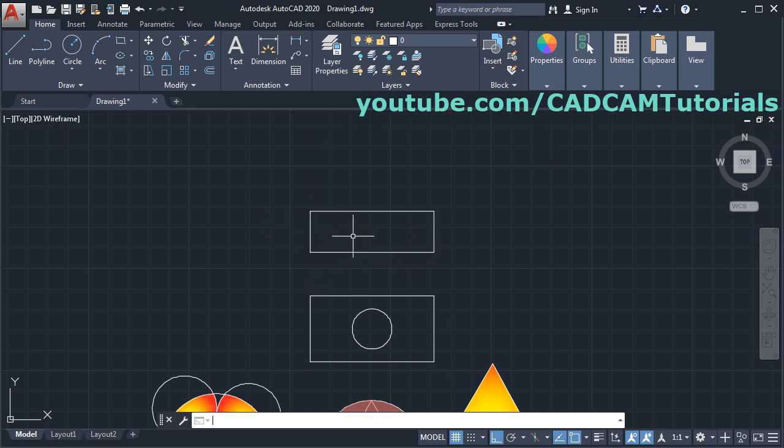Then press enter to repeat the last command. Then for this portion, take your cursor to this quadrant, take it above, click on this intersection point, take it above, give the height. Then again take your cursor to this quadrant, take it above, click, and now if you click here, it will connect to the midpoint.